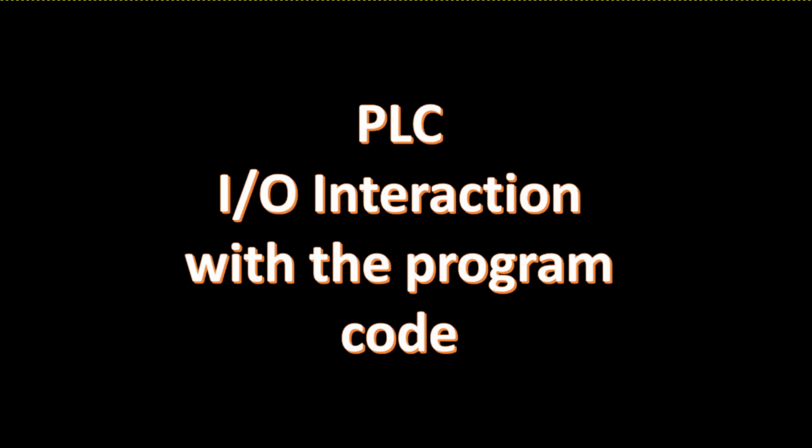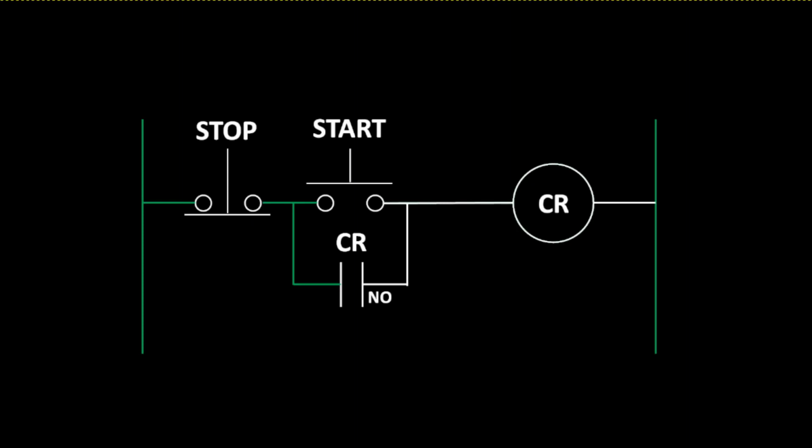What we're going to do in order to understand this reaction is build a simple start-stop circuit, where we know that the stop push button out in the field is a normally closed device, and these push buttons are going to be momentary.